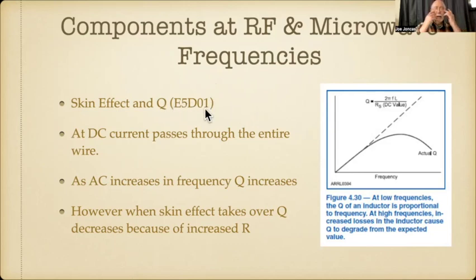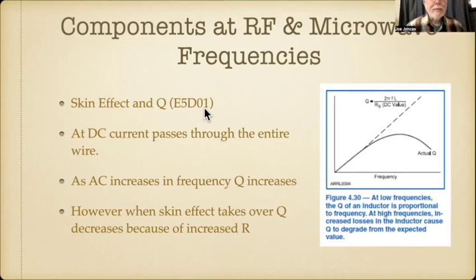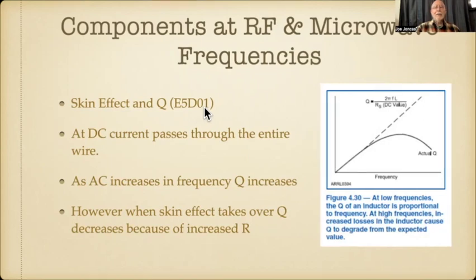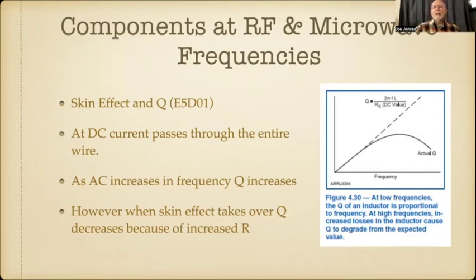You will notice in a lot of these transmitters that use coils, the coils are silver plated. Silver is a better conductor than copper. So if you have silver on the outside, most of the current is running in that silver that's just plated on the outside. Well, you need the inner portion of that wire for structure, correct. But other than that, that's all.